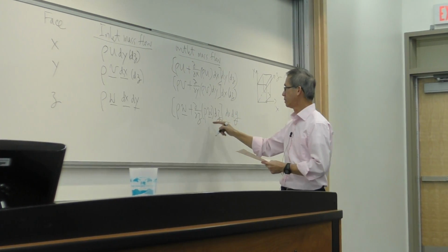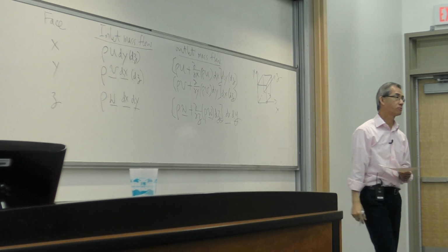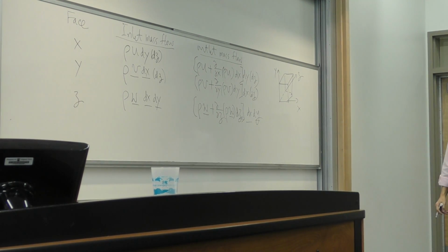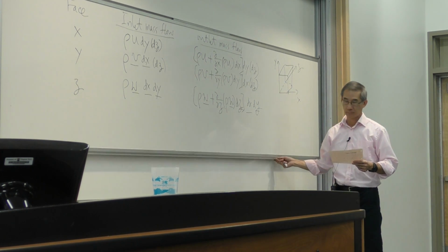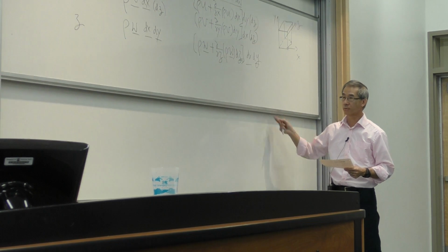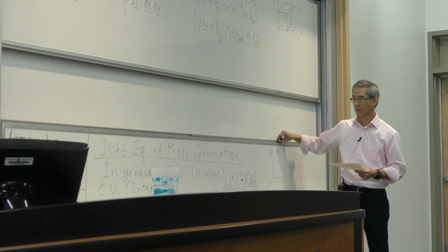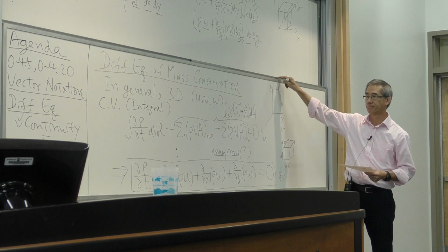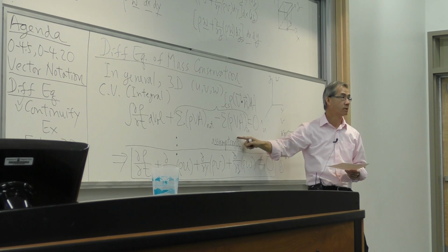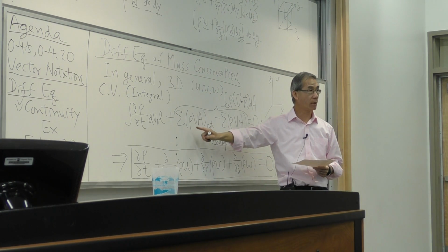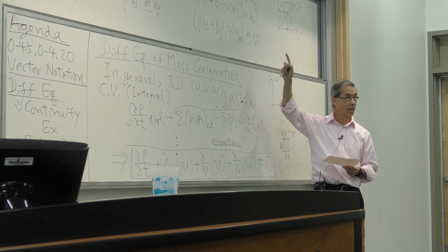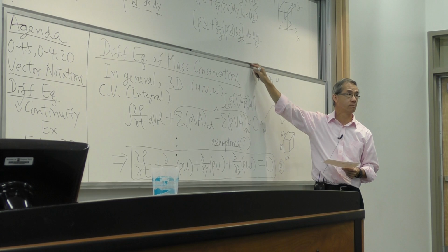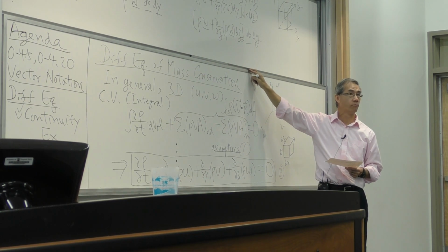And the change is with respect to z, so this now completes my 3-dimensional analysis of mass flow in versus mass flow out. That sounds familiar to what we started with for the control volume shown here. This is mass flow out minus mass flow in. And I did it. The difference is I did it in the differential volume.